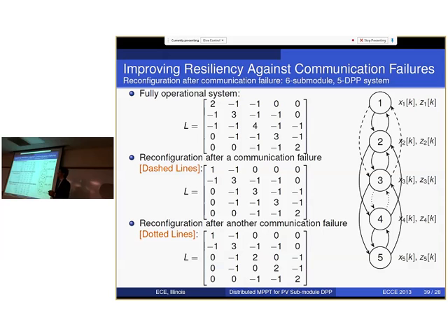Well, that's what I'm saying here. Yeah, the bare minimum is neighbor to neighbor, like 1, 2, 3. So of course, you just communicate with them. Okay. So each one here you get extra neighbor to neighbor plus neighbor to neighbor. Yeah, so basically, for example, if this neighbor-to-neighbor communication link fails, but you can still talk to this one, and talk to this one, this algorithm will still work. You just need to have a minimum of at least one communication link.